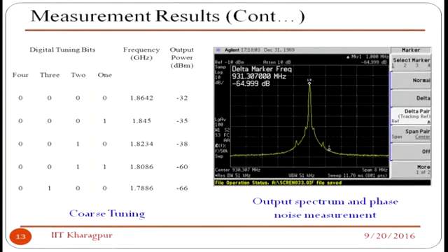Later on, one PhD thesis came out of that, on how to reduce the spurs, and that is a very interesting work carried out by one of my PhD students. I will explain when I design the frequency synthesizers. But remember, more or less, this is the spectrum of a very standard VCO at 900 megahertz or 1.8 gigahertz before the divider.